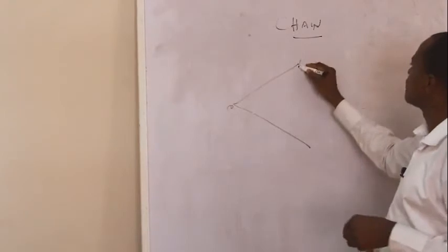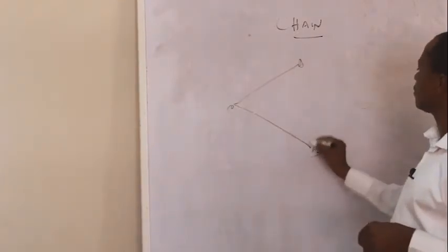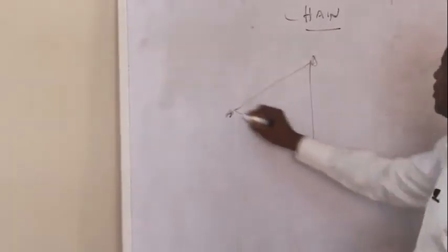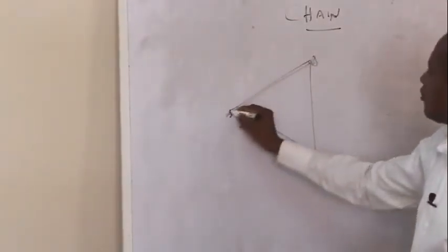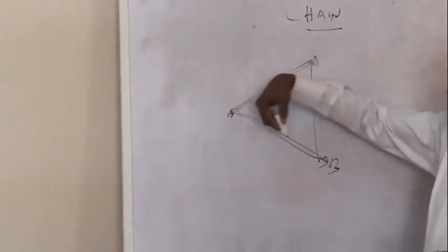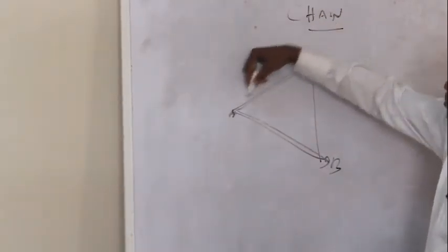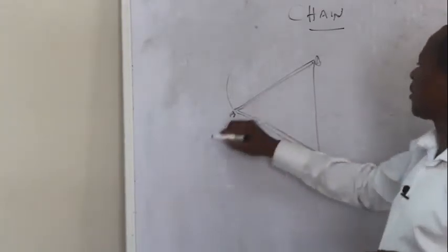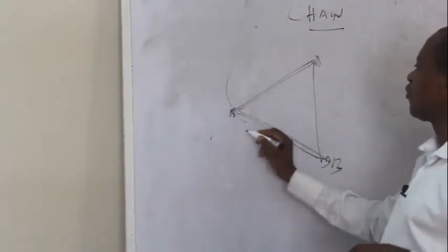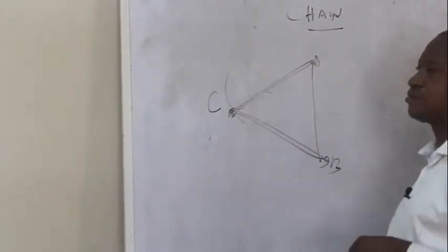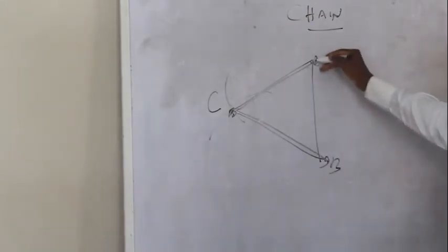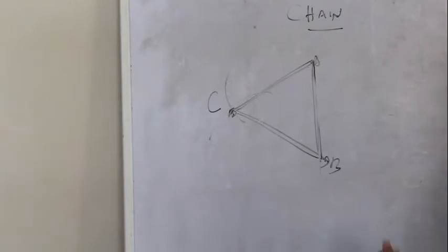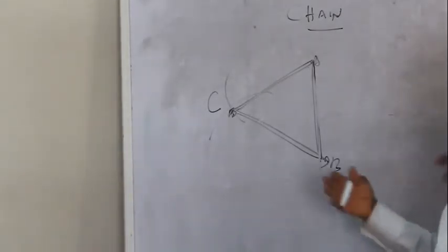This point is known, but we don't know this one. We can carry out measurement from here to here, measure out for this one. And if you know the scale, you can make an arc there. Here, you can make an arc there. The intersection will help you to fix this point. It's purely linear. This is the baseline which we have determined by chaining 2 or more times.